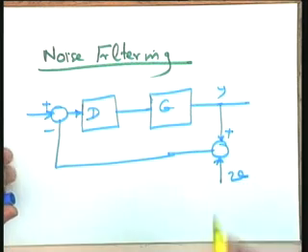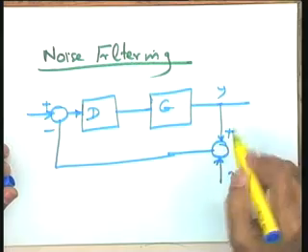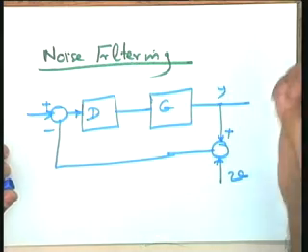This V is a high frequency noise, high frequency signal which is coming because of the sensor. Recall the temperature control system. Thermocouple being close to the tank which is being continuously stirred. Well, you see, you cannot avoid high frequency signals entering the loop, because after all temperature measurement is a must, and to measure temperature you have to install a measuring device. Suppose you install a thermocouple there, so you see that the thermocouple is introducing the high frequency noise in the loop which otherwise was missing in an open loop scheme. So it means a sensor is the major source of high frequency noise in the loop.